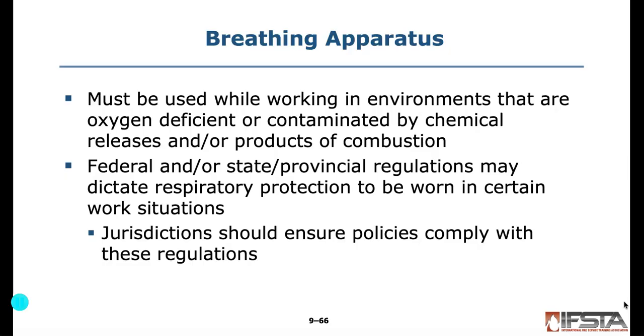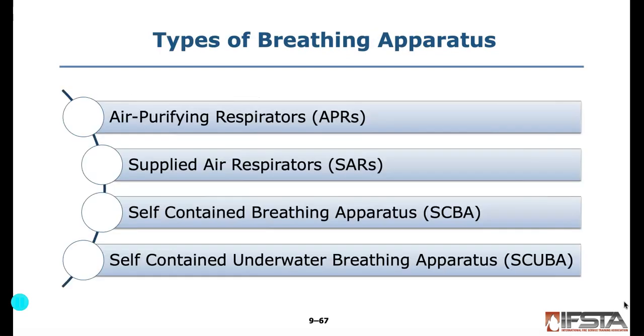Breathing apparatus must be used while working in environments that are oxygen deficient or contaminated by chemical releases or products of combustion, also known as IDLH, immediately dangerous to life and health. Federal and/or state or provincial regulations may dictate respiratory protection to be worn in certain work situations, and your jurisdiction must ensure that your policies comply with these regulations.